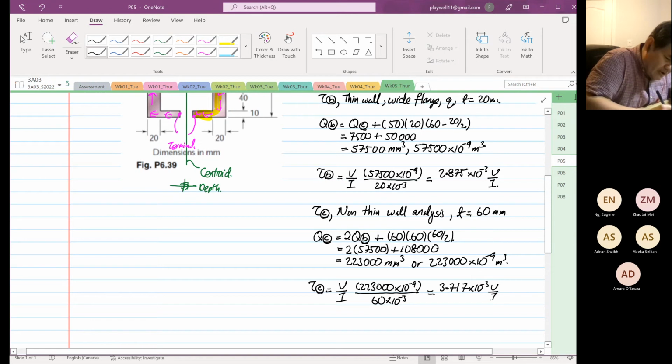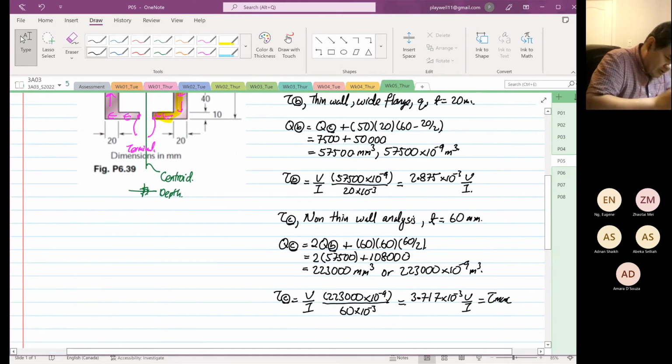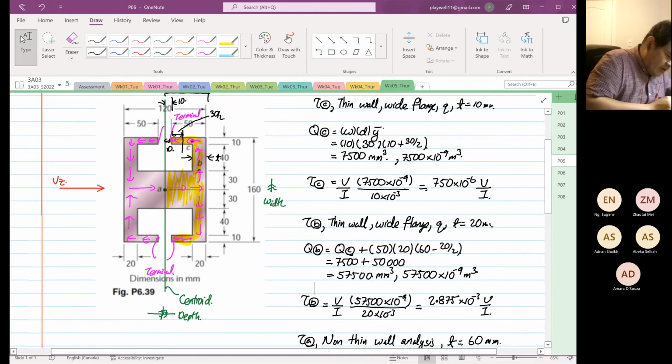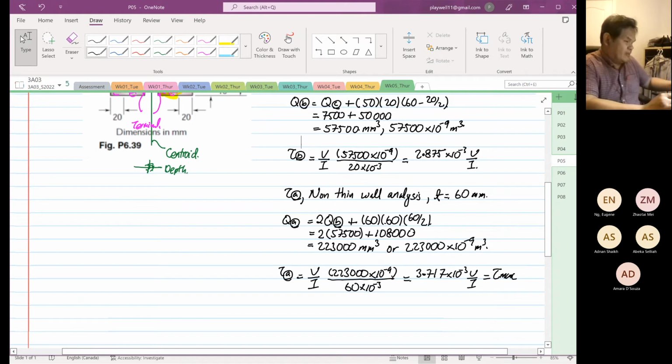Now, this at point C is at its tau max. Hey, is it point C? No, point A. I do apologize. Okay. Shear stress at point A. So now our shear stress at point A is the biggest, right? Before that, in the previous example, when the shear force is vertical, the maximum is at point B, but now horizontally, the maximum is at what? Point A, right? Okay.